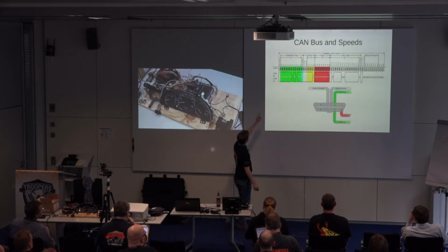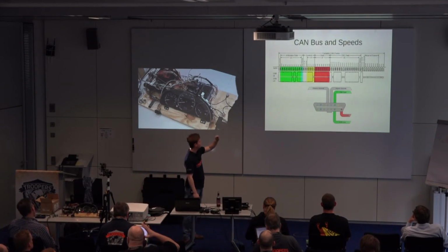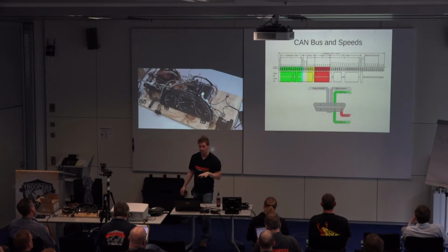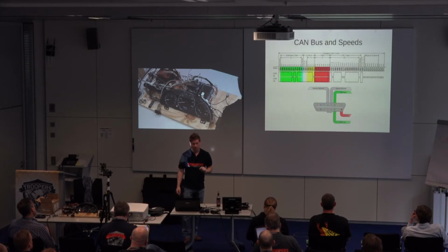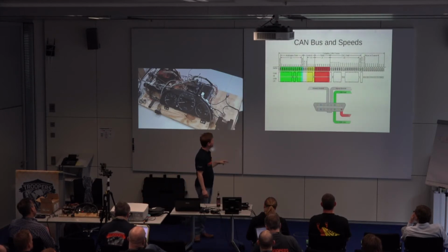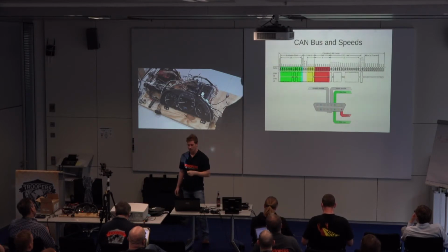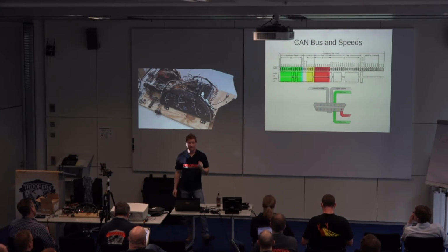Up here where you see the CAN high and CAN low, the way they're working is whenever a bit comes in, a 1 or 0, they're going to separate at the same time. One goes up a volt, one goes down a volt. And that is to get rid of noise. This way if one goes up and the other one doesn't, bad packet, bad bit. So the nice thing about this is it's a twisted pair, 2-wire system. The resting state is 2.5 volts. It's a very weird state. And it only goes up 1 volt. So it's very, very easy to find. If you're looking at their car wiring system and you see 2 wires twisted together and you test it and it's averaging at 2.5 volts, that's CAN.